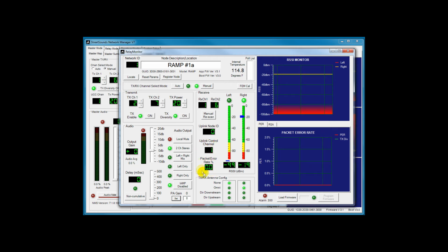And then if you're dropping packets, if the signal is way down in the mud and it's down in the minus 85 or 90 dBm range, you will get a packet error rate. You're dropping the signal coming from the uplink channel. And that will show up here, and it will also show up in the packet error rate graph we'll go through in a minute. So that's something to keep an eye on if you got a low signal. There are ways of configuring things.